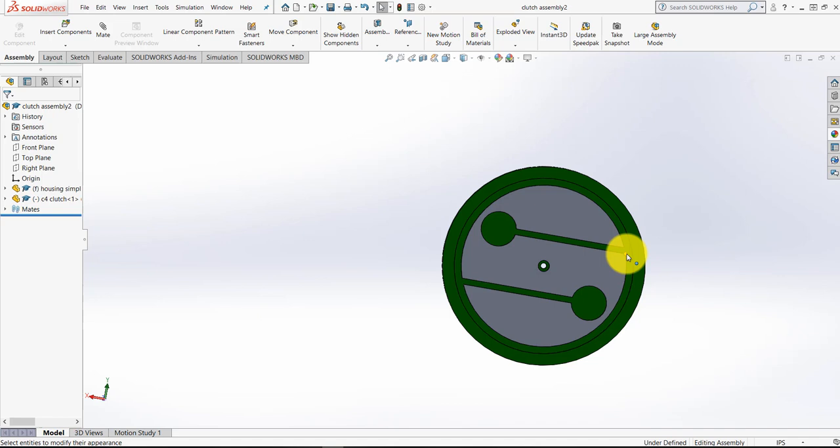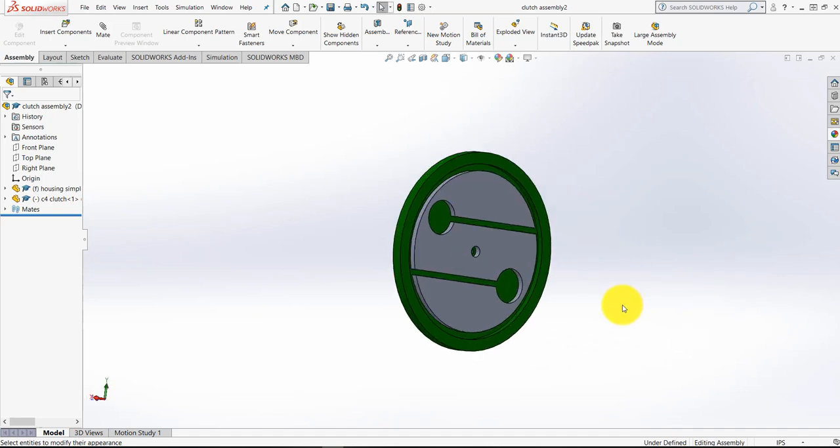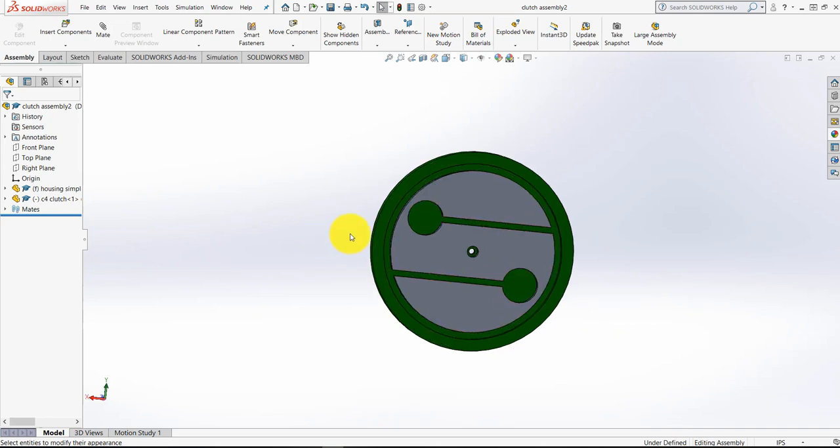So I can do a few things to try to simplify the models. I can do them either in the CAD program or in SpaceClaim, and I'll leave that up to you. But in general, I can trim it. I can cut things away. You could create some features and suppress them later, when you want to export it.